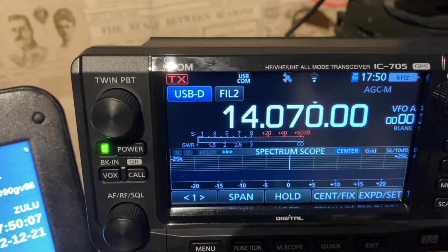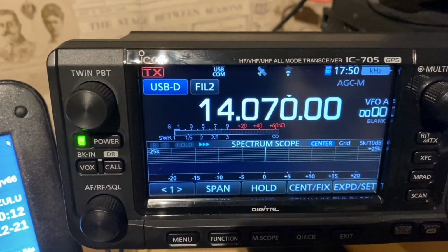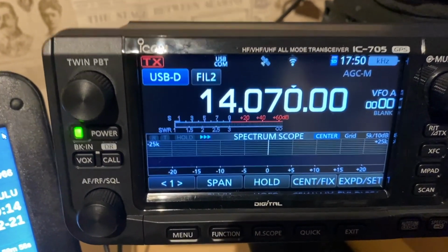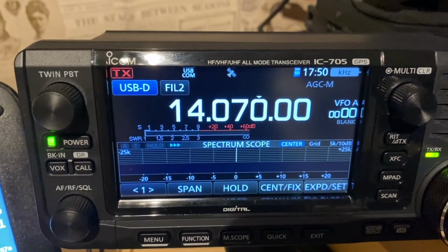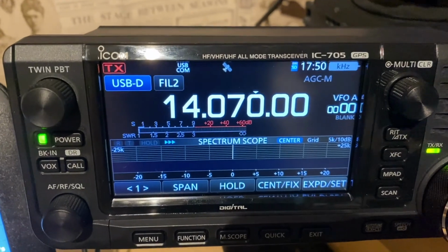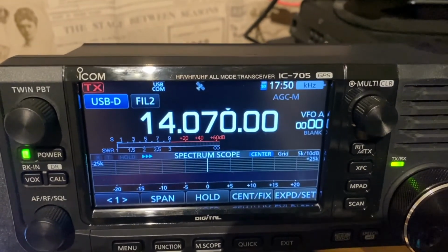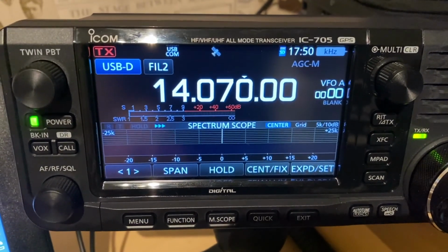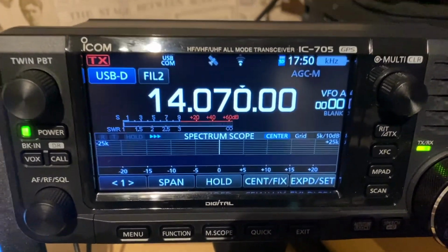There's a little bit of a quirk when you start FLDigi. If you leave it on a VHF or UHF frequency, anything that's not HF, and then you go to start it up, sometimes it seems to get a little upset and it won't initialize the CAT control properly. So just to avoid that happening, the final part of any of the scripts that I run effectively sets the radio back here. You can set it any way you want. That's entirely your choice, obviously.